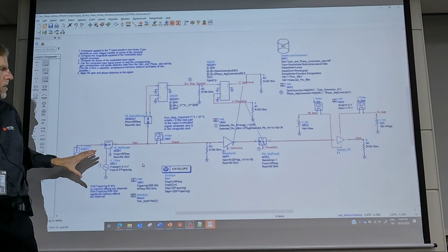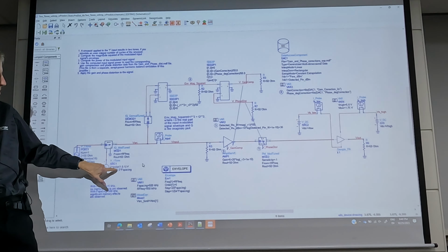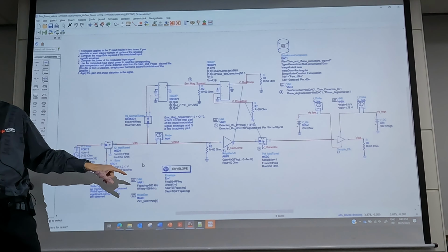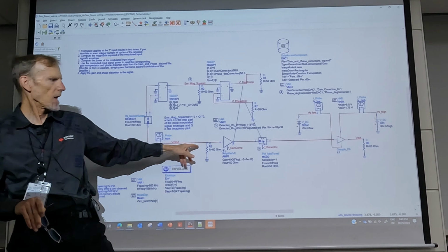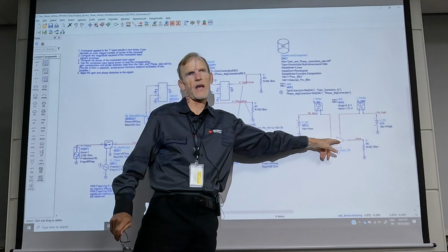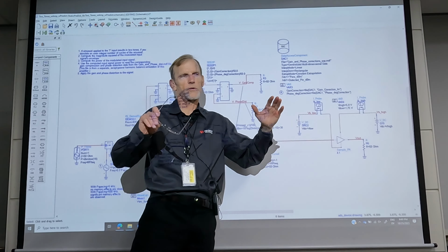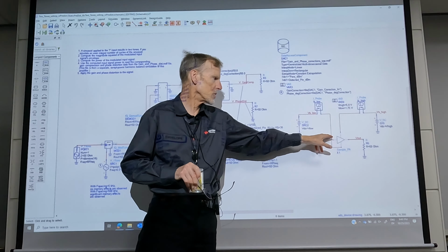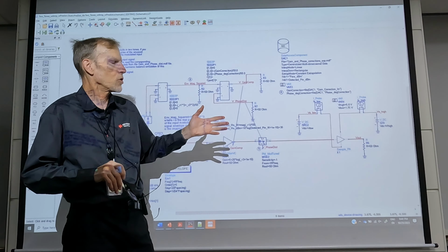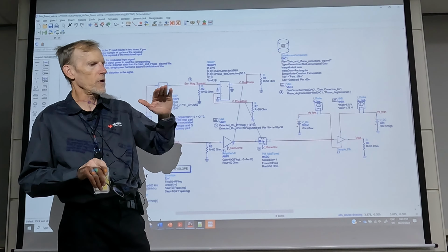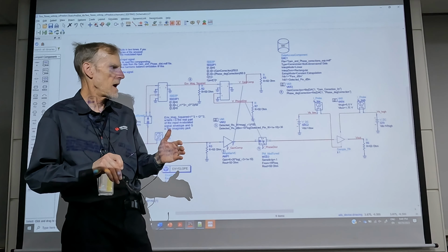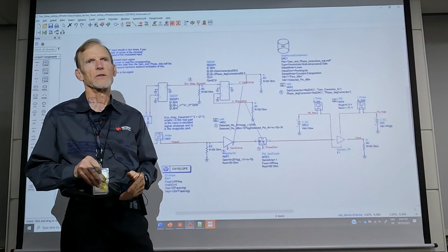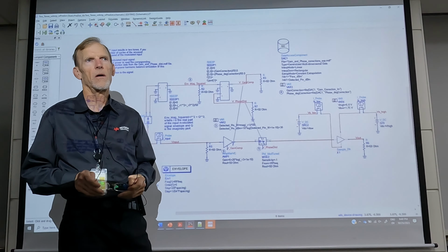And then as you set the tone spacing wider, memory effects are more likely to appear in this amplifier. It's more likely to show up. So you can see, after correcting for the first order, the static AM to AM and AM to PM, how much memory remains in the amplifier.